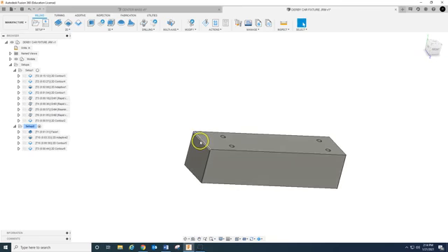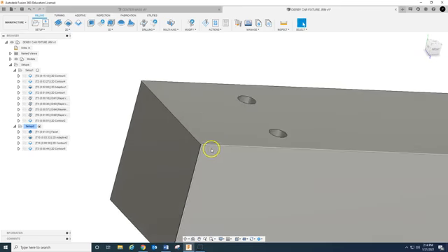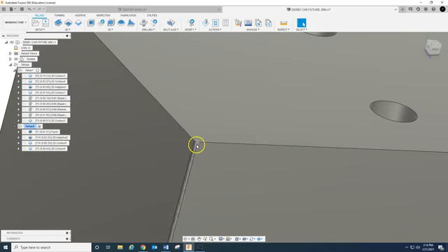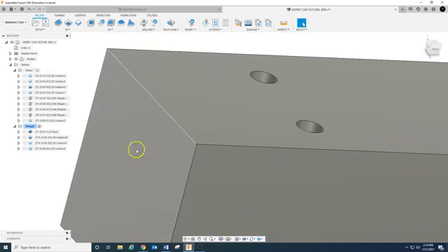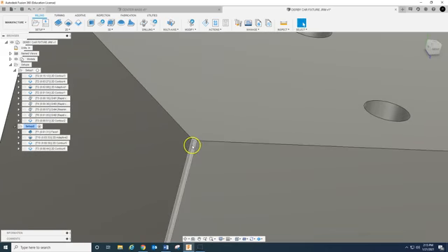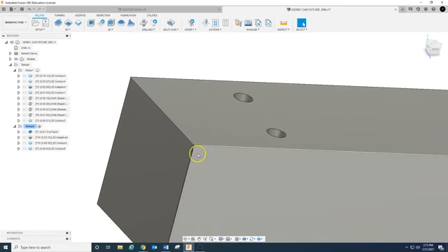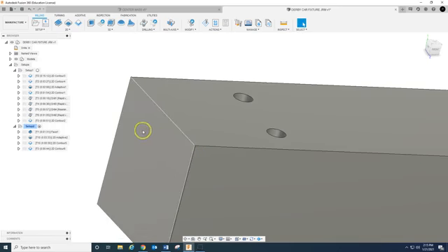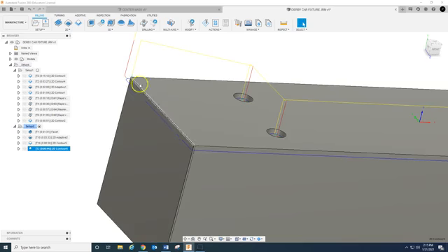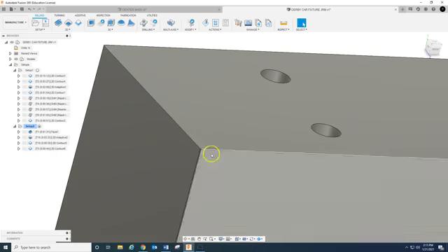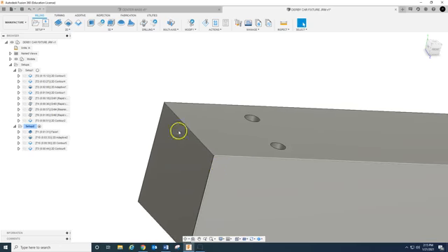And one of the things worth pointing out when you're designing something: I try to design out sharp corners the best I can. Had I left that corner straight, then I would have to file it. We want to let the machine do all the deburring for us whenever possible, and then of course go in with the drill mill and kill those corners. And when you're chamfering edges, you don't have to draw the chamfer in if you don't want to, but it's easier if you do. Okay.